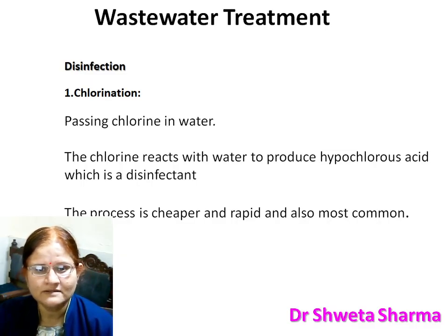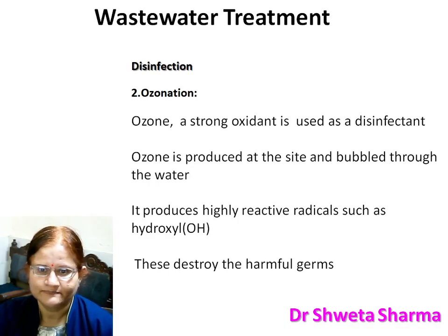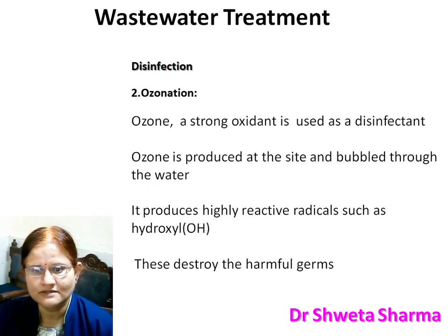The most commonly used technique is chlorination. By passing chlorine in water, we generally disinfect water. This process is quite cheap and it is the most common step for disinfection of water. The second step is ozonation.